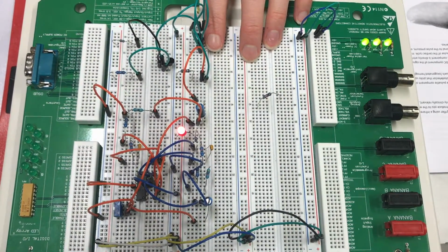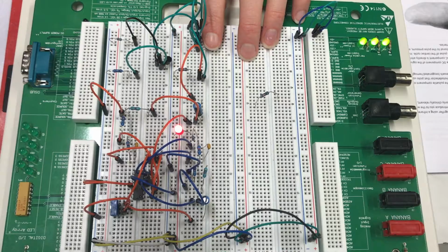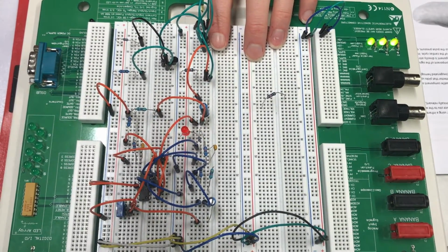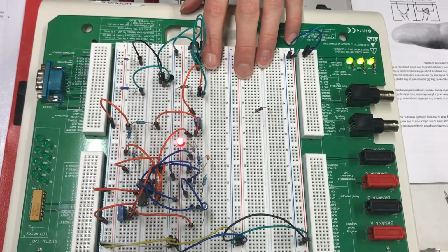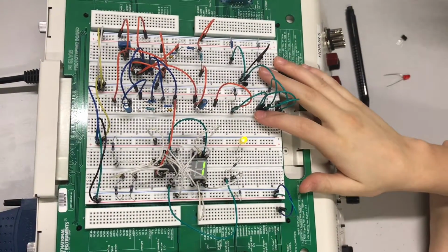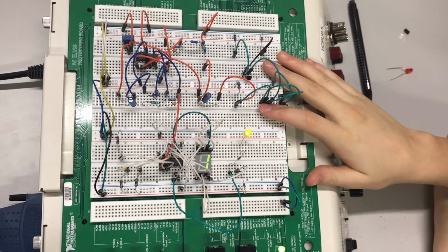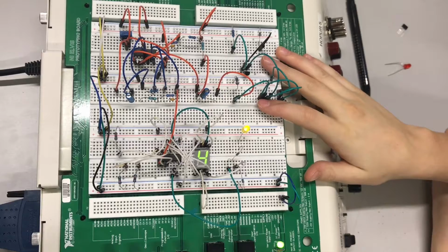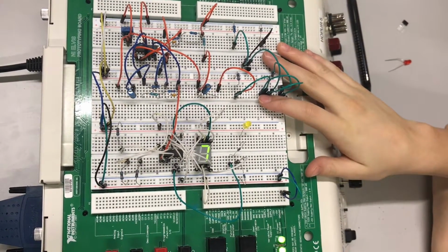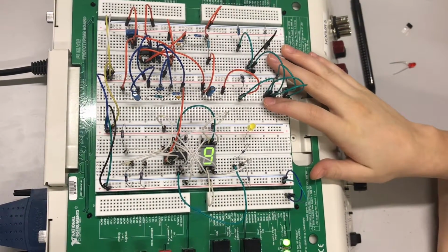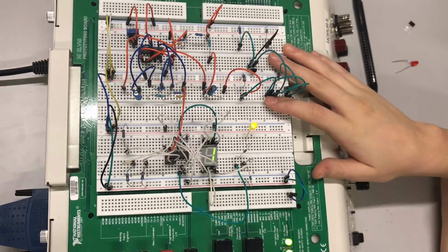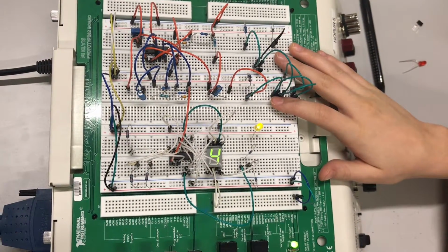Here we can see that when a finger is put on the sensor, the LED lights up in the same rhythm as the heartbeat. In part 2 of the exercise, we added the 555 timer circuit that we built in exercise 3 to our photoplethysmographer. With this, we could record heartbeats per minute, both at rest and after some exercise.